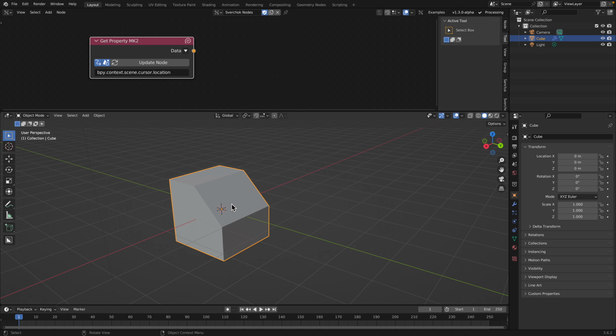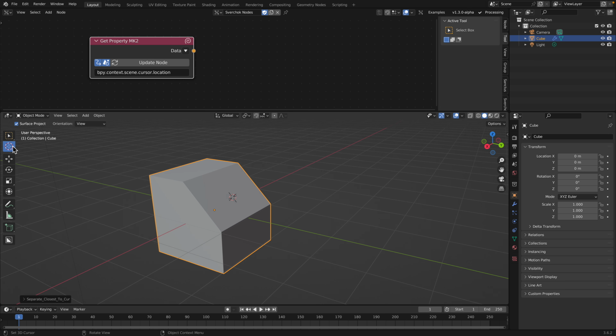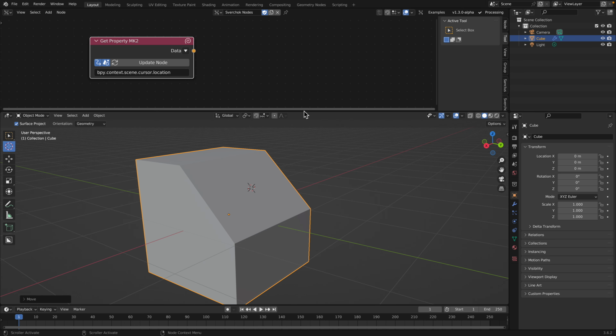and we want to just look at the position of this 3D cursor. We can use shift right click and that repositions the 3D cursor, or we can use the cursor tool and set it to geometry, and then we can drag this thing. In recent Blender, we can actually drag it and it's going to slide through the 3D surface instead of clicking it. Okay, so that's something to understand first.